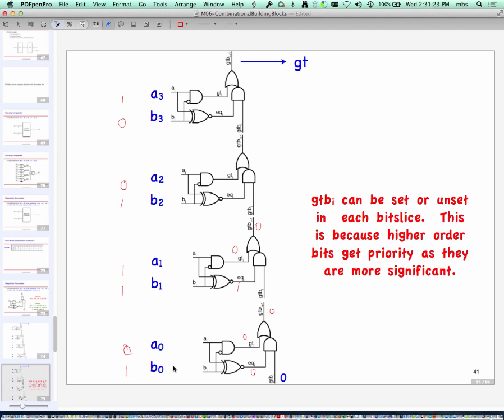Let's try the next stage. So I'm receiving a 0 here. What will I get out here on the output of XNOR? 0 because they are not equal. And what will I get for the AND? 0. And therefore everything is 0, we get a 0 out here. Finally, what will I get here? X0, 1, and 1, all 0, I'm going to get a 1 out there, right? So in this case, by the time we reached the end, we got the right result.